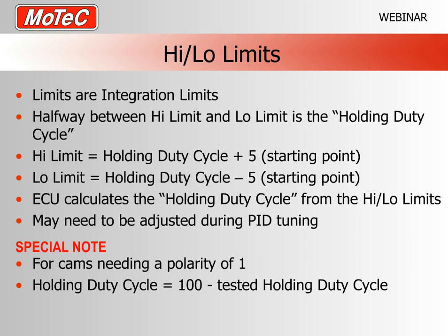It'll try, it'll sort of look like it's moving, but it just will never get to your aim position and the control won't be real great. Like, I've seen this a number of times. So you have to do that test first off. If I turn up to the dyno with a new engine or one that I haven't been involved with the setup, the first thing I'll check, I mean it only takes about 5 or 10 minutes, is go in and do that auxiliary output test just to make sure that what is set up in the high-low limits is correct, because if the high-low limits is incorrect, the thing won't work properly.